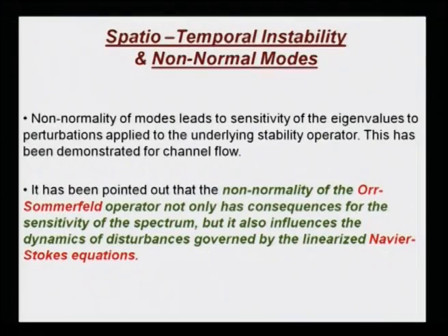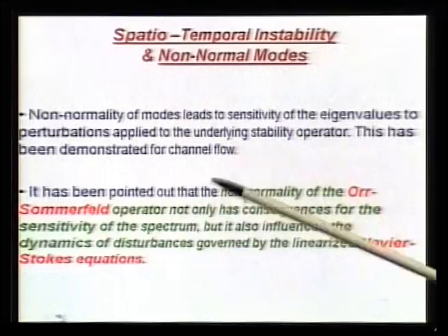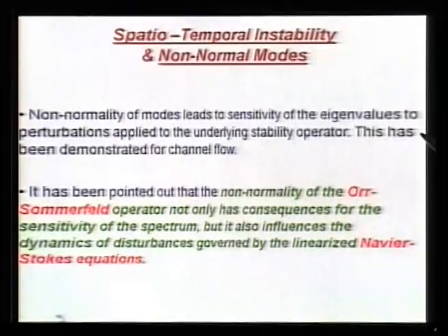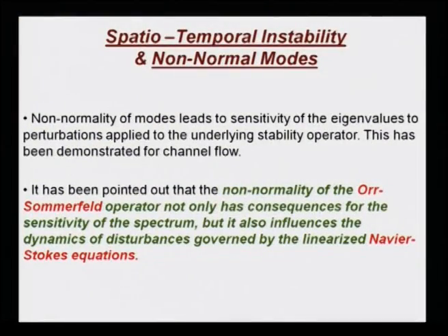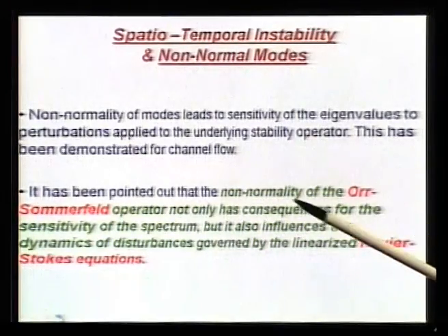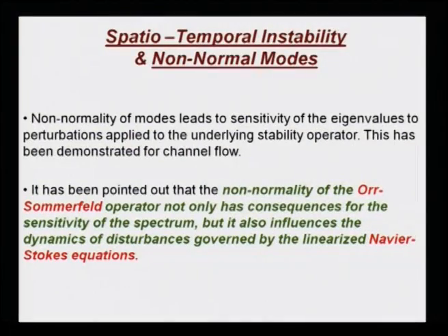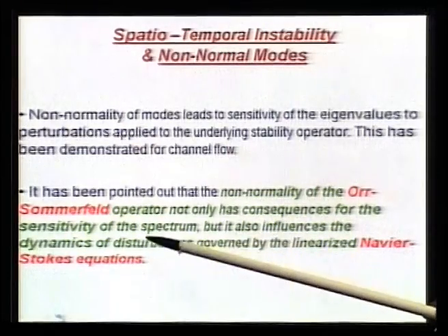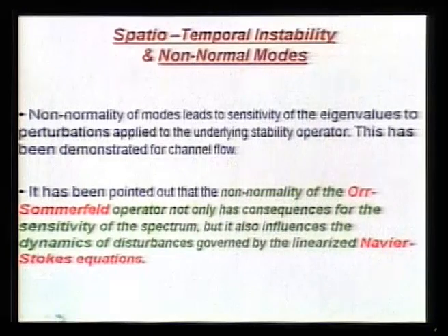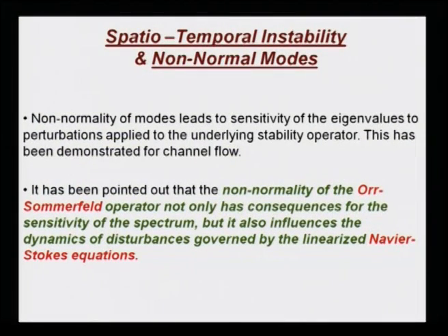Despite that, it has been noted that when you have non-normal modes, they make the system very hypersensitive to background disturbances. This is due to the property of the stability operator of the governing equation. And some calculations have been done for channel flow, and it has been shown that this non-normality, via its sensitivity of the spectrum, shows completely different dynamics from that given by the linearized Navier-Stokes equation.